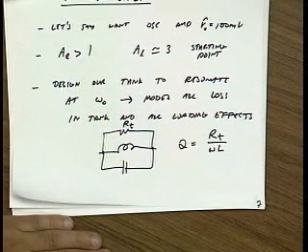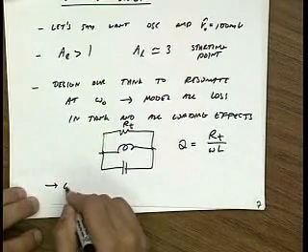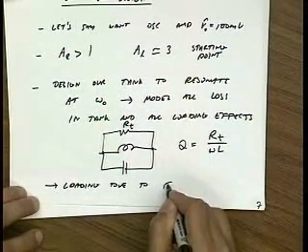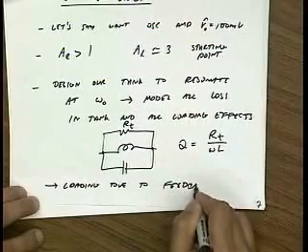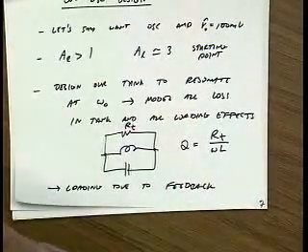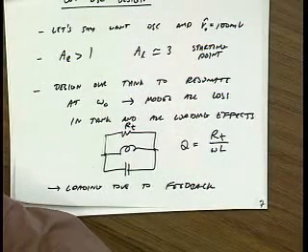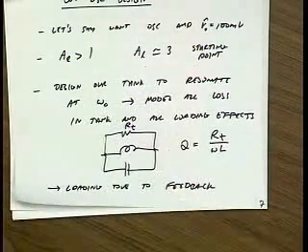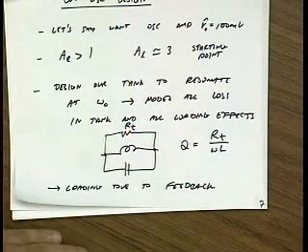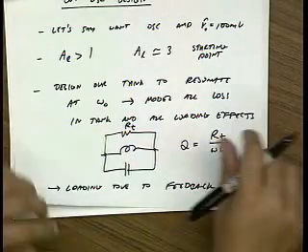And if you have feedback, as we saw last lecture, you have to be careful to include the loading due to feedback. So in the case of the transformer feedback that we looked at last lecture, the input impedance of the transformer appears at the tank through the transformer winding ratio squared. So you have to make sure you include that. Okay. All right, so the next thing we do is we estimate